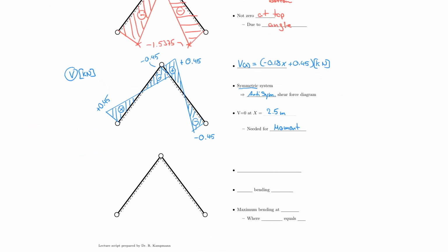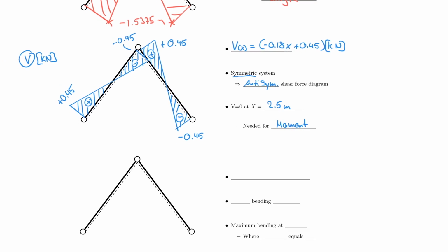So with that said, I can move on to my moment diagram. Just as before and as always, I can bring down my maximum or minimum values, or like where my values will be maximum or minimum. And so I have that intersection there and this intersection. And my moment diagram will be fairly simple to draw now, because I know it's 0, I know it's 0, I know it's 0.